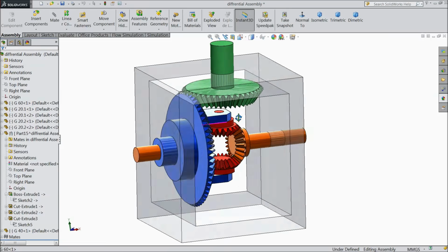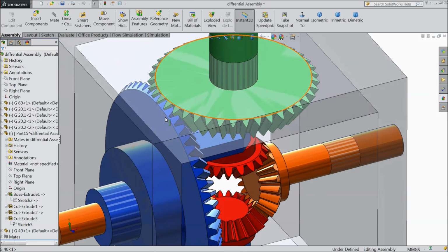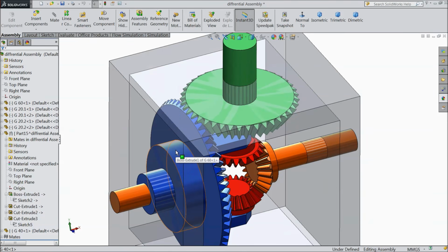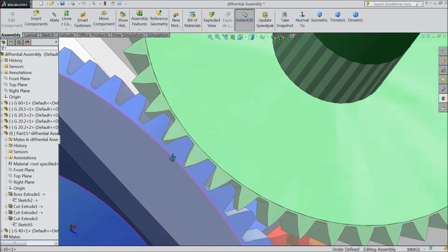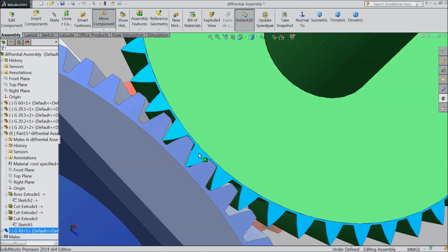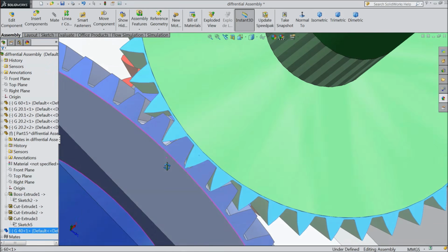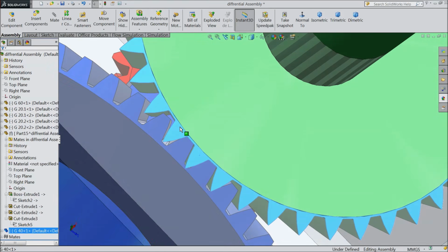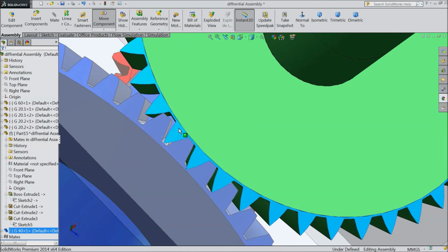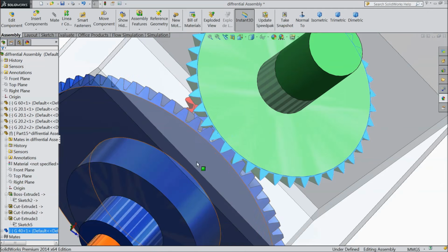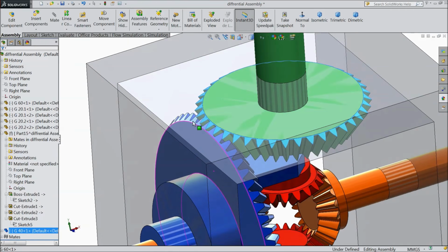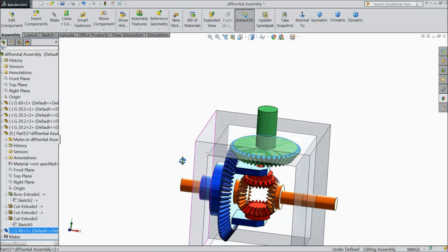Now we will assign the gear ratio between this drive shaft and this G60 gear. So first choose the proper position. Just shift the gearbox according to the place, or you can select it by making some relation, but we want to save some time, so we will just adjust accordingly by hand, manually.